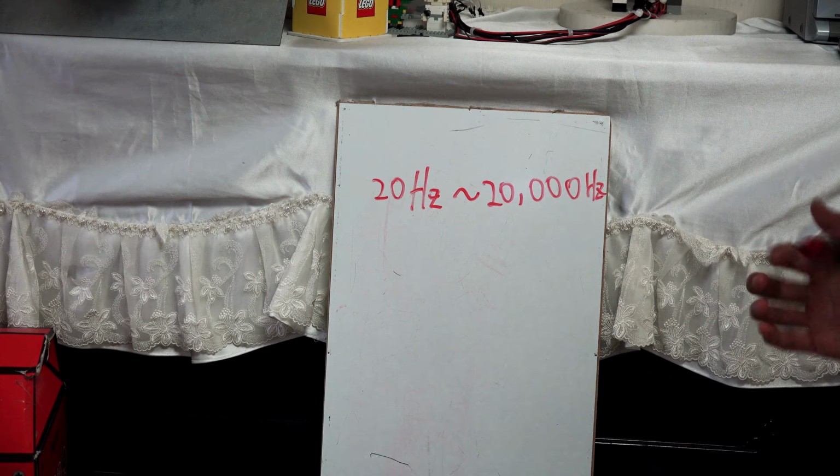So after all, we have the distance in centimeter equal to the duration from pulseIn, which is in units of microsecond, multiplied by 1 per 29, and this is for dividing by 2.